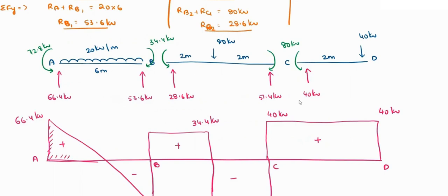You can just shade this shear force diagram like this. This is how you are going to represent it. Where the moments are not getting influenced for calculating the shear force, only the reactions and the external loads that are acting will come into the picture. So this is the entire shear force diagram.